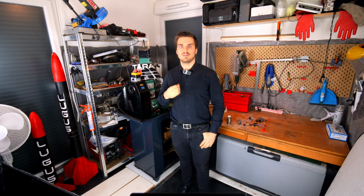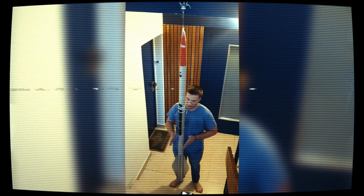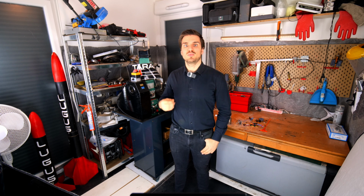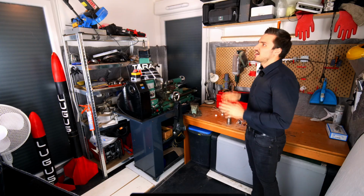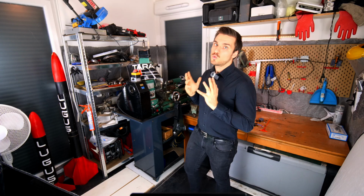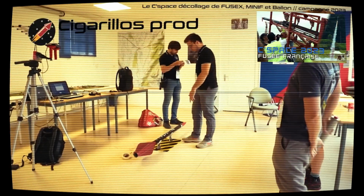And after doing all of that, we perform the final test where we ordered the motor to go into saturation. And once saturated, we launch the new PID with anti-wind-up. And when the system returned to the control range, the rocket stabilized, so the test was successful. And after all of that, we were able to go to the Sea-Space campaign and launch this rocket.